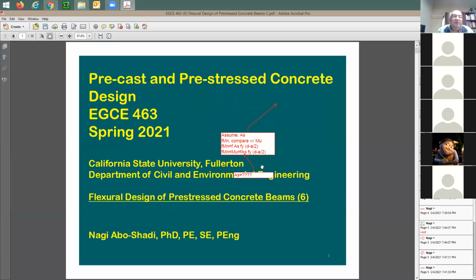All right. So we'd like to do something very similar to this. In the previous problem, here's the way it worked: we said, let's balance a certain amount of load. If you recall, the way we came up with the number of 7 strands, I said let's balance 90% of the dead load. That was an approach, just to think about balancing the load and thinking about deflection. But here I'm going to say, no, let's use the stress efficiently. Because after you came up with the number of strands, you started to check stresses, top and bottom, at the initial and at the service. And then you say at the end, yeah, it is lower than the limit. This is good.